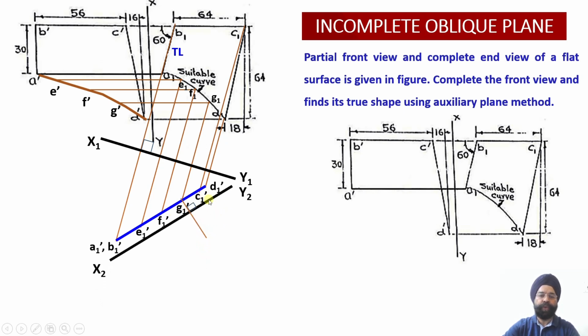this. So again I am going to leave around 10 millimeter distance over here between this existing edge view and the new auxiliary plane. So this was AVP, so this plane is now AIP. Why? Because we have drawn it parallel to the elevation projection line. So this is my elevation auxiliary view. So any view which is drawn parallel to the auxiliary view, for the front view, this will be AIP. So the new auxiliary plane, which is my X2 Y2, which is an AIP, has been drawn.